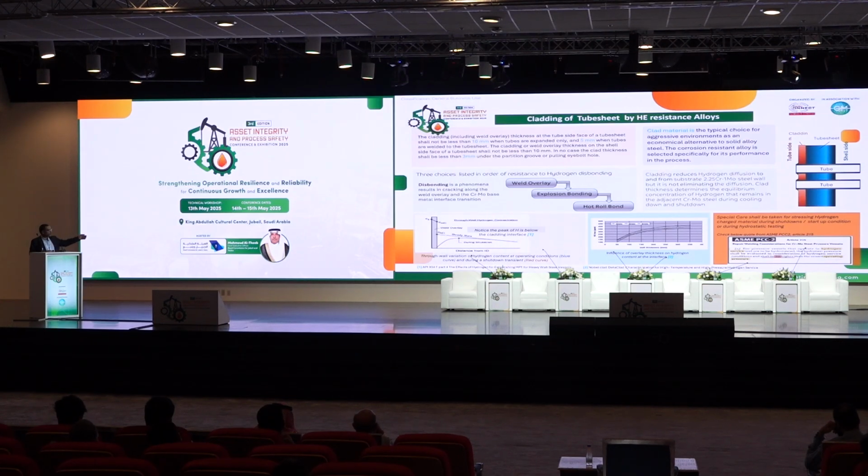And if you are doing this, you need to think about how it can impact decreasing the diffusivity of the hydrogen. It will not be immune. You need to think about the thickness of the weld overlay which should be applied. And also, as you can see at the bottom right over there, the note from ASME PCC-2: even during inspection, if you are doing a hydro test on a chromium-moly steel material that was exposed to hydrogen, you can put the material at risk by the inspection activity itself.